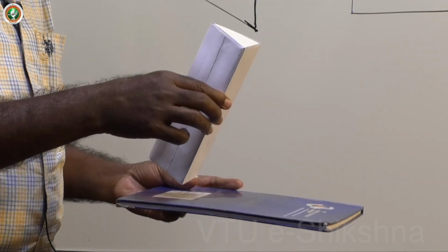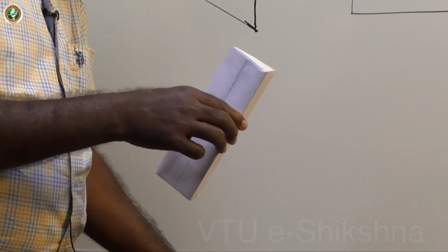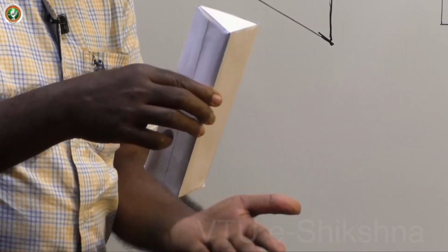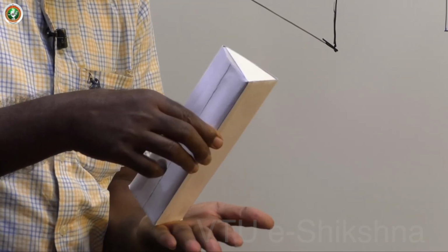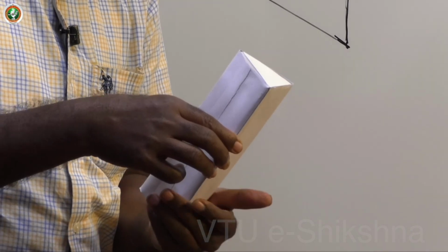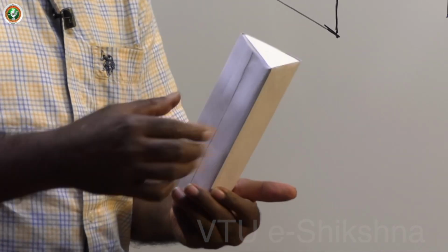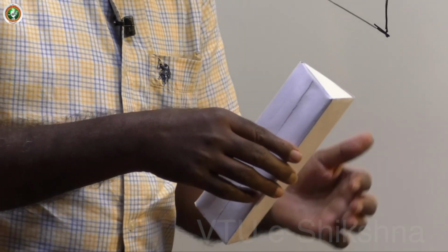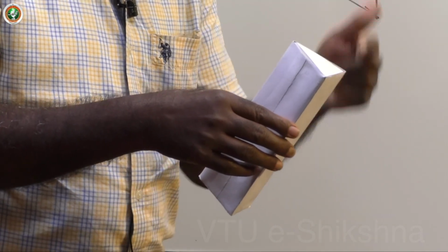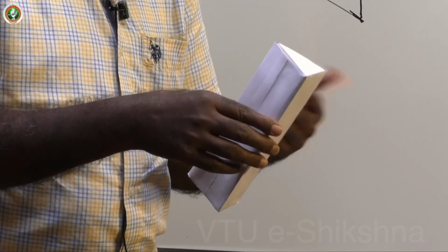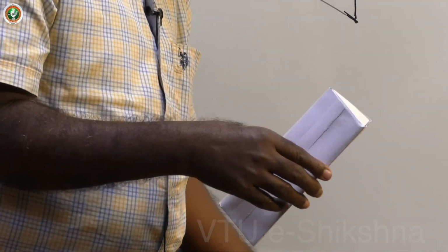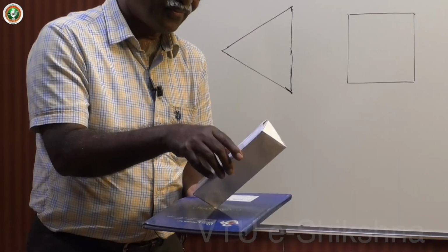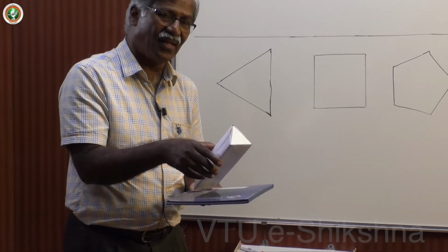Or they may refer to this particular reference, that is, the rectangular face containing the base edge on HP is inclined at some degree to HP. It is very similar to the axis. See, the axis and this surface are parallel. Now if it gets 45 degrees, the axis also assumes 45 degrees and vice versa. That is one item. The next item is this, the corner on HP. That is a different position. We will discuss it in the later stages.